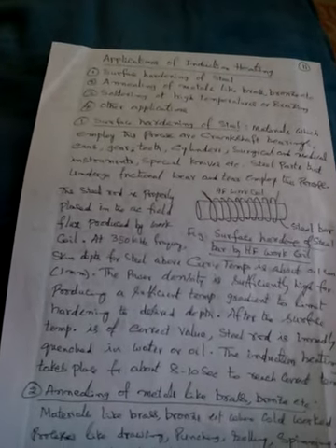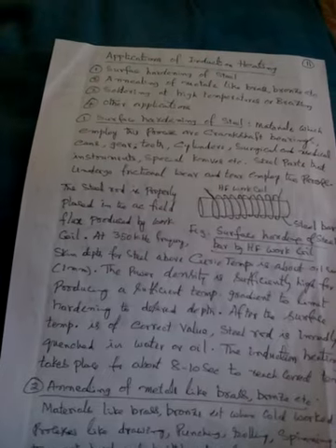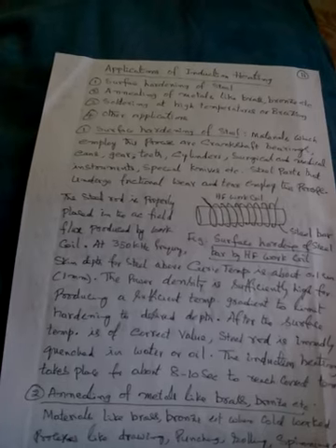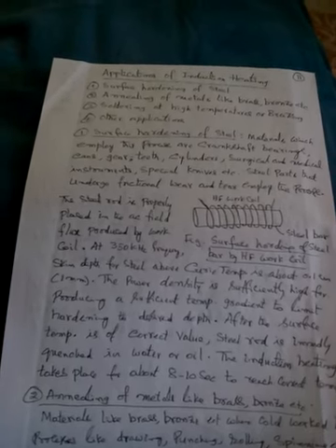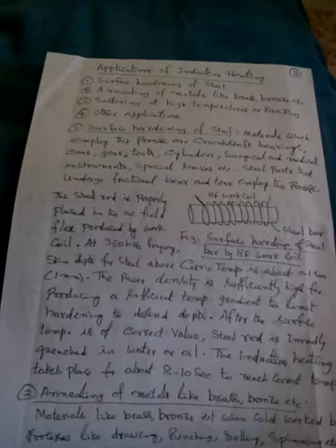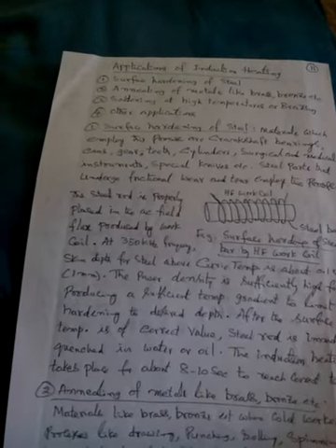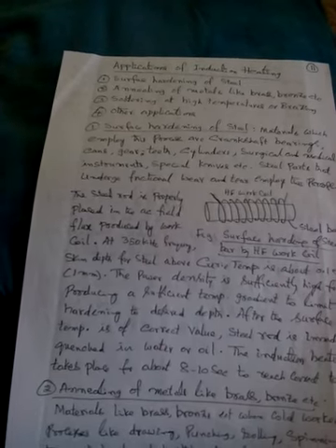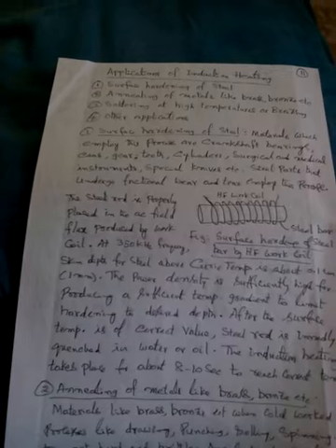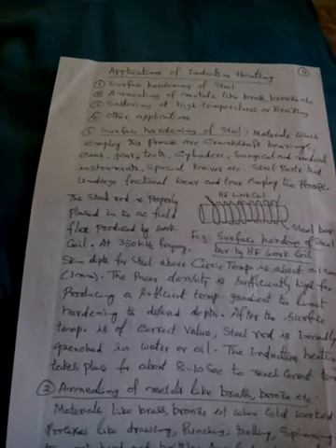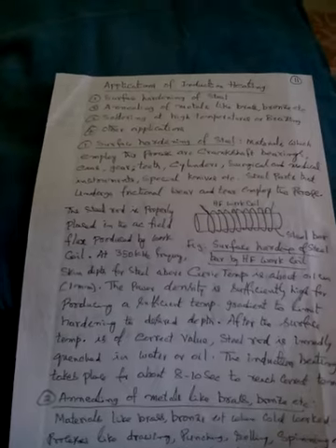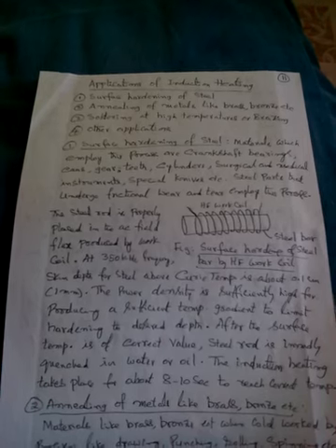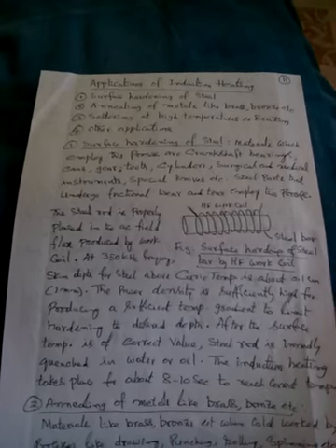There is a method, of course, for cooling the heat also. There is provision for cooling. Again, heat will be produced within seconds, and within 1 minute we can process and harden the surface of the steel rods. Every 1 minute, one rod can be hardened, so it is very fast. We can process a large number of such steel rods using this method for surface hardening purpose.